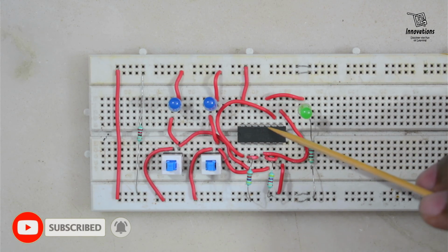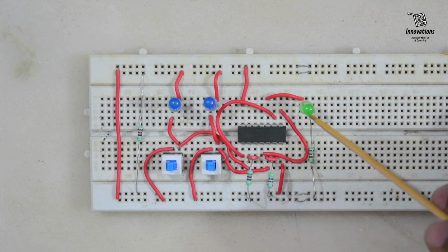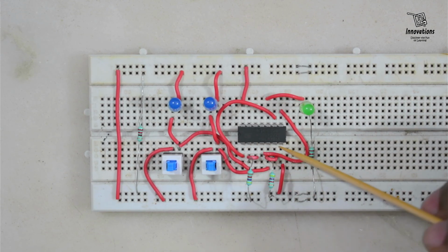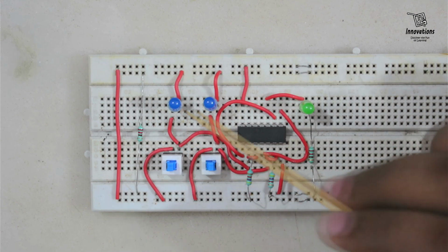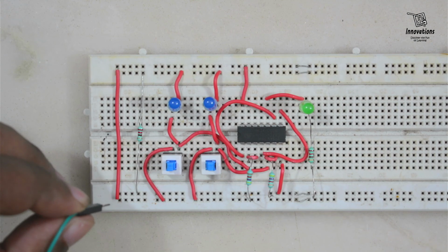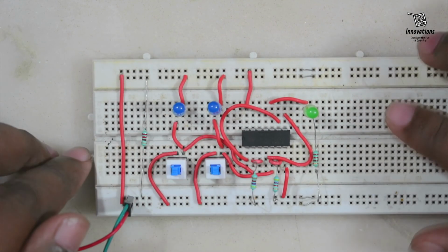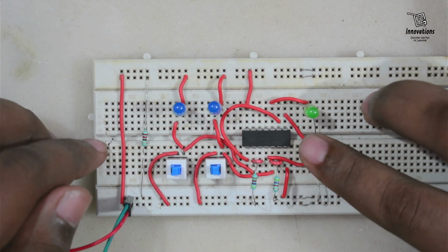And the output from segment 3, pin number 10, is then connected to the output status LED, and the rest of the circuit is the same. Two pull down resistances are used in two segments, and one current limiting resistance for the output LED and one current limiting resistance for the input LEDs. Now we will connect the power supply, 5 volt, and test. This is the negative power supply and this is the positive power supply. These digital ICs work on 5 volt, so do not give more than 5 volt, the ICs may burn.